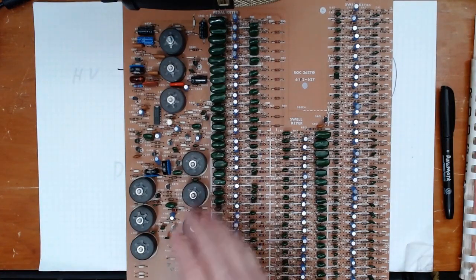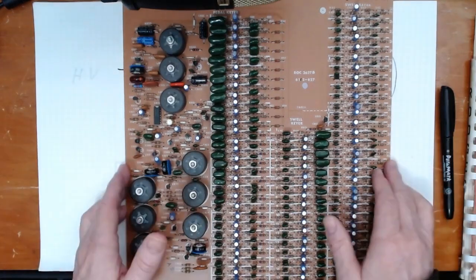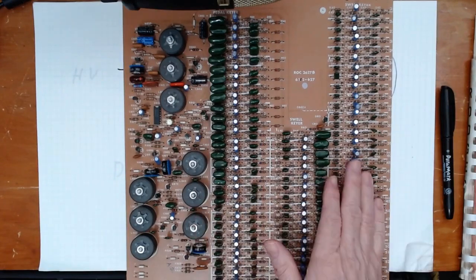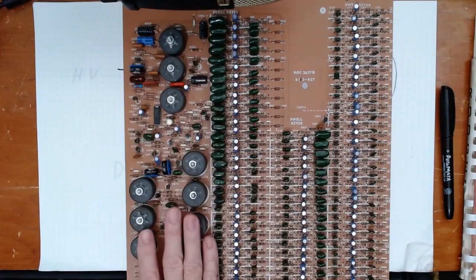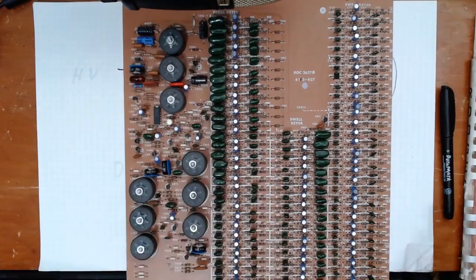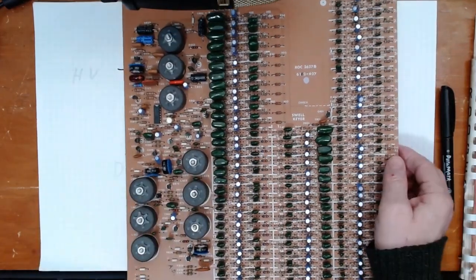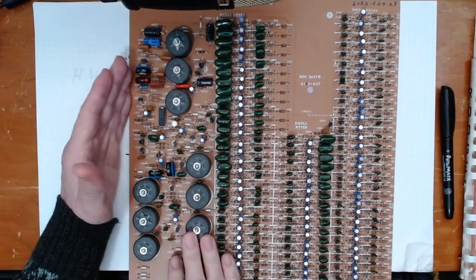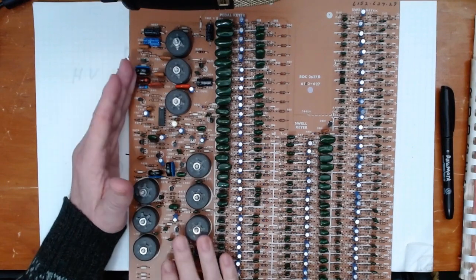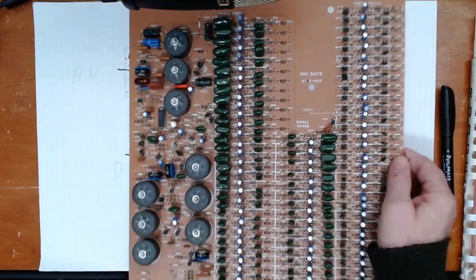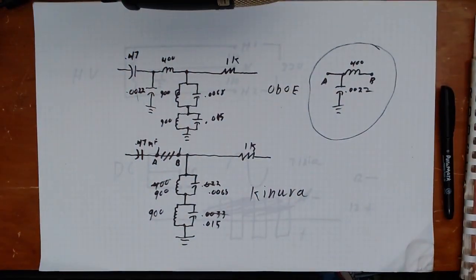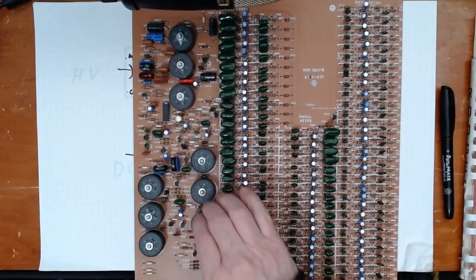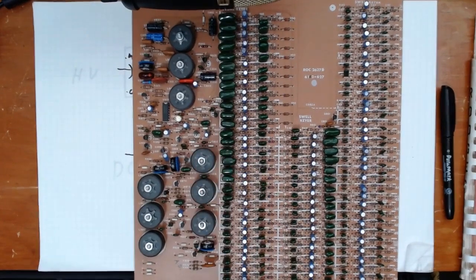So what I'm going to do, now let me back up just a skosh. I had thought that, well, maybe I can just route the 33E's output into these filter circuits and get these voices. Well, no. Remember I talked at the beginning of this video about the polarity orientation. These circuits are oriented for positive keyed, and the original is oriented for negative keyed, and it does make a significant difference. However, the individual coils themselves, they don't care.